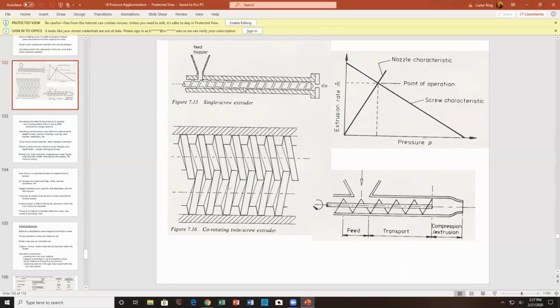So two options: I can go with a twin screw extruder, which mixes, but the screw will have mixing pins in them, or have the geometry change as you go down. Different flights, some back pumping actually, large contractions and expansions going on, anything to disrupt the flow.